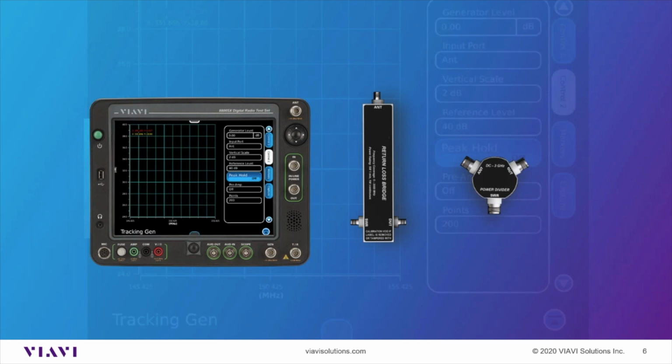The 3550R has a built-in return loss and VSWR measurement that it can do without the use of an external bridge. It also supports the use of an external bridge. But what's built internally is a completely different type of hardware, and it is more susceptible to high power or interference at a site.